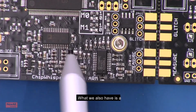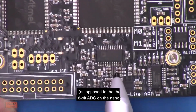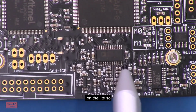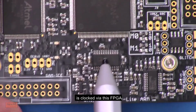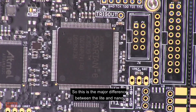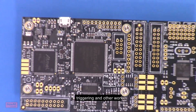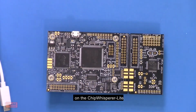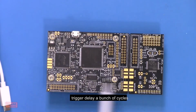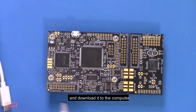What we also have is an ADC up here. This is a 10-bit ADC as opposed to the 8-bit ADC on the Nano, and it can run up to 105 megasamples per second on the Lite. The Lite's ADC is clocked via an FPGA. This is the major difference between the Lite and the Nano. This has an FPGA on it, so we can do a lot of nice triggering and other work on the ChipWhisperer Lite. We can trigger, delay a bunch of cycles, and then record that data to a buffer and download it to the computer.